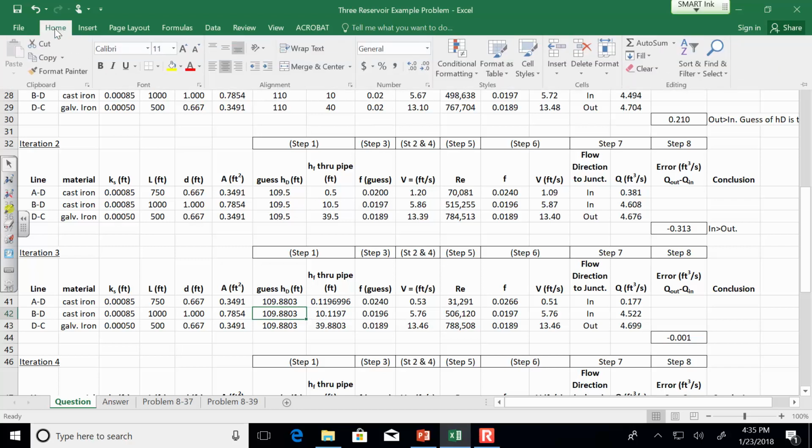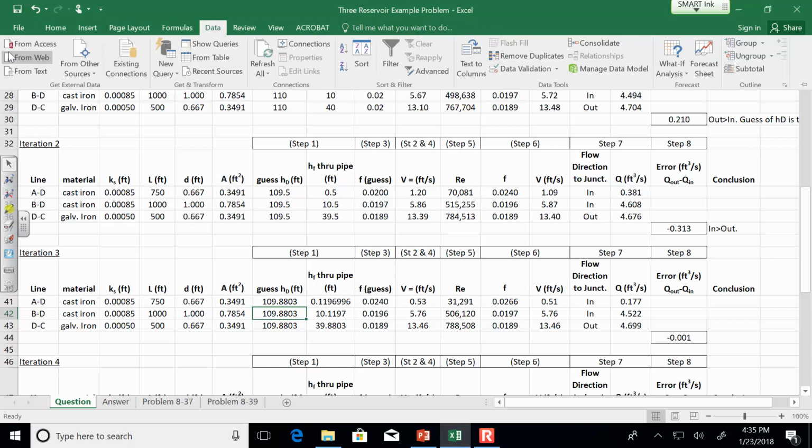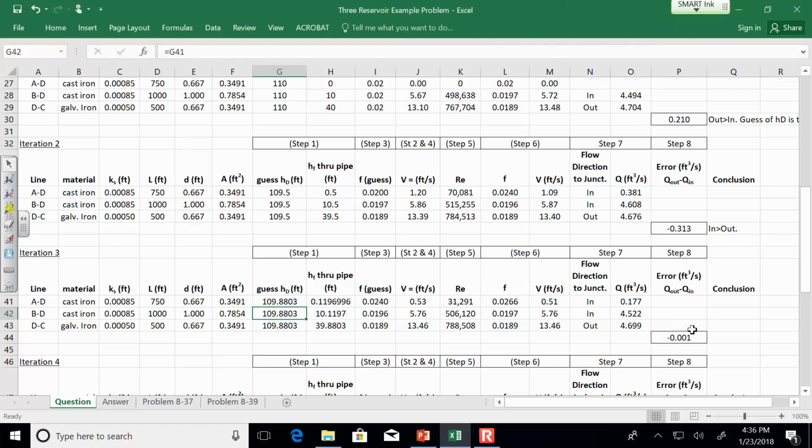By the way, what's the other tool that's similar to Goal Seek? Do you remember the name of that? Solver. Solver is more sophisticated. And when I was doing this earlier today on my own computer, I had previously set Solver so that I wanted the answer to be really, really precise, and it was too precise. It wouldn't calculate the answer. It could never find a solution that was accurate enough, and so it kept failing. So I had to change the precision. And I guess down here on this machine, the precision was already set so that it would converge.